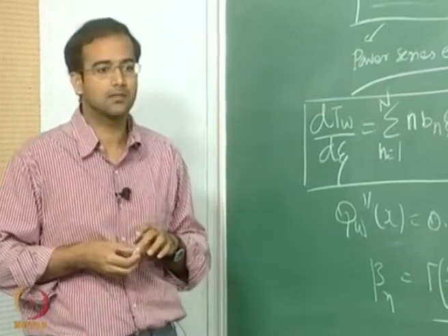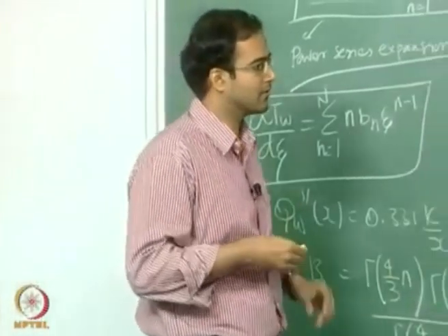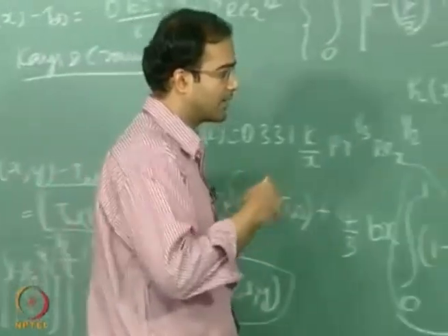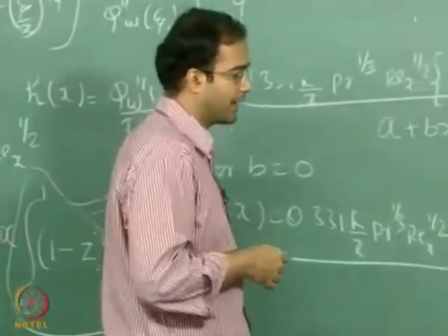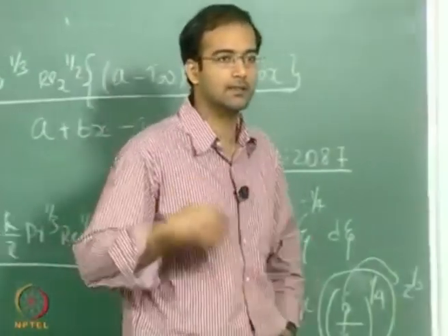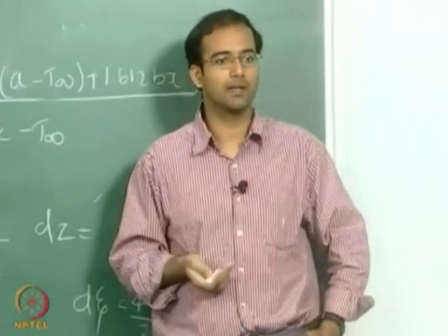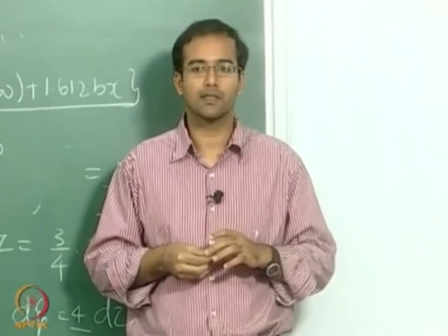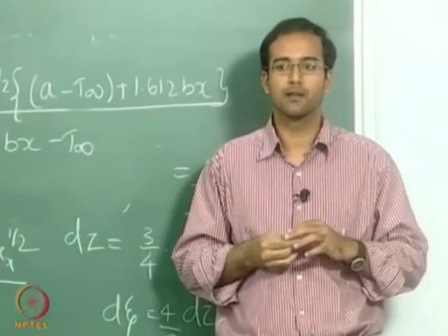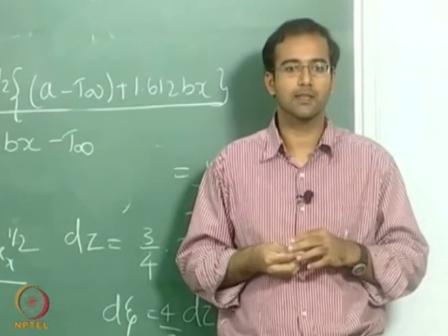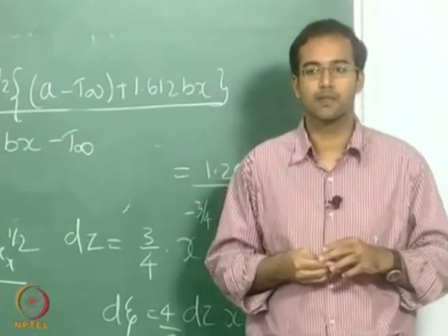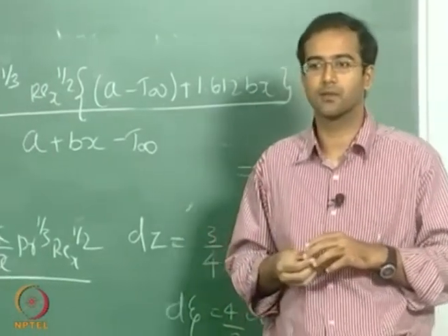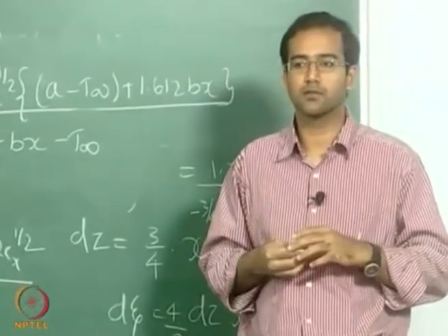That is also very important and interesting because, although there are many external flow problems, in most of your practical problems in heat transfer, such as heat exchangers, you will be encountering internal flows. In those cases you should understand the approximations that you can make and how you can get the expressions for the local variation in the Nusselt number, and, in the fully developed case, how there is no variation in the Nusselt number, and so on.